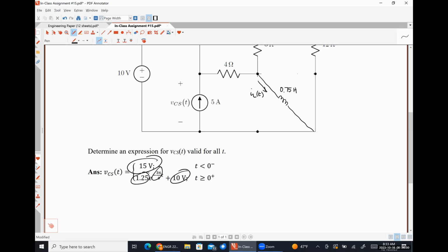Another thing that I want to point out here is that there's this little red switch, and you can slide it back and forth. It needs to be on the 1x setting, not the 10x setting. Otherwise, your numbers will be garbage. So just make sure that this red switch is slid upwards towards the tip as opposed to downwards towards the cable. It also literally has printed on here 1x and 10x. We want the 1x setting.